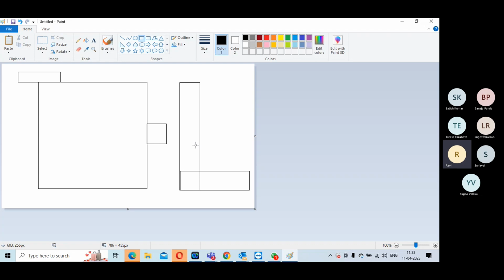If it has to buffer, what will it do? We should let the standard cells through. If you are putting a macro there, that's when you are putting off your interviewer, who will say it's not dealt with. Intuitively you think, hey, this is a common area, place the macros. No. Will you ever place memory in the center? That is wrong. That should be the least option. Unless it is really required, you will not place the memories at the center.